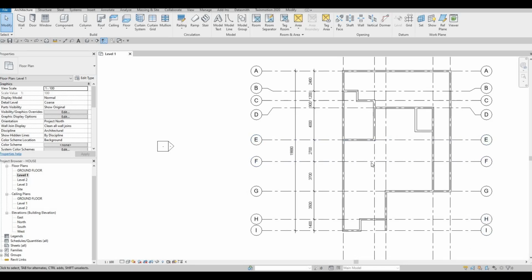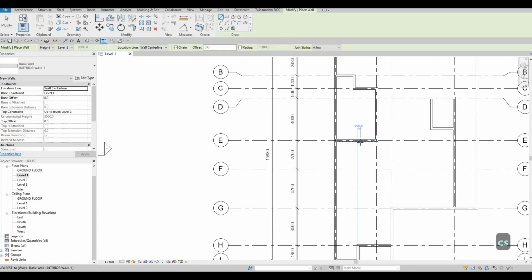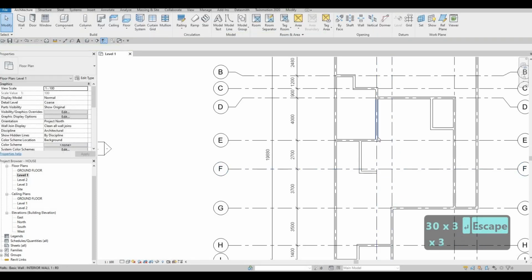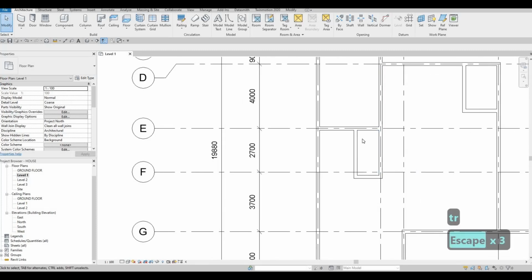So now that we have that, we could add in something right here, CS on the wall. So we already have that. That's easy for us to manipulate. We're going to add a wall right here. This will be around maybe 3000. So I'm going to make this one 3000. And then here, I'm going to close this off, TR, so it goes all the way there.